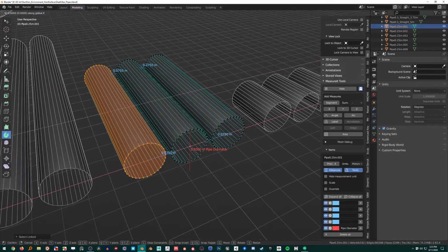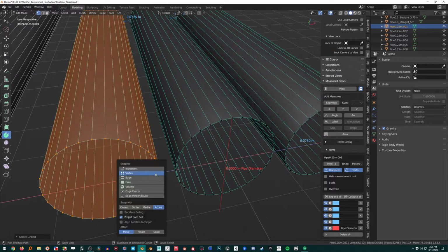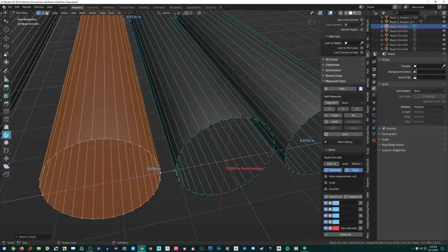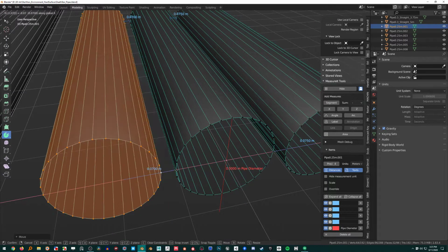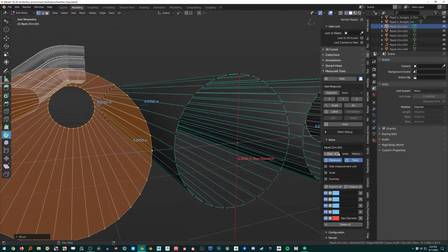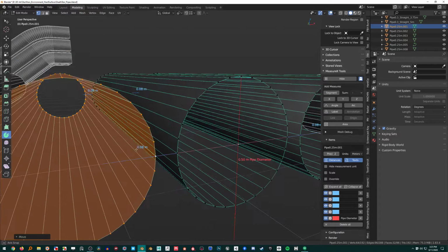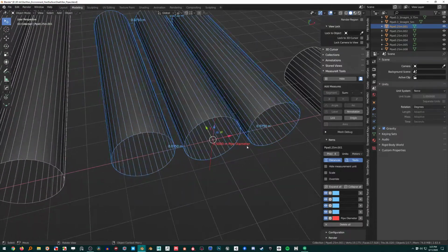Sometimes they were slightly off, like that. So I would just grab this whole thing, change my pivot to active, and then snap to this, and then G X minus 0.075. Oh, and another thing, this precision thing, it should come out like this, precision of 2 decimals, or yeah, I don't know, decimal precision. So I just boosted it up so then I could get more precise.